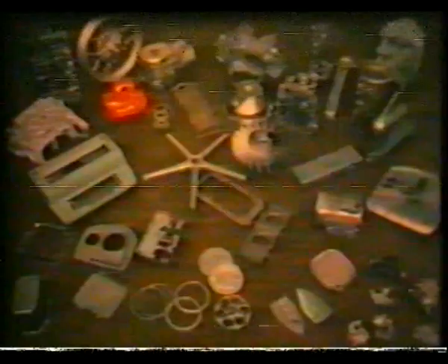The die casting process allows large series of non-ferrous components to be produced with great accuracy and very economically. In the process, molten metal is fed into the shot sleeve of the die casting machine and squeezed by the plunger into the die cavity. The liquid metal fills the die, duplicating the most minor details of the cavity. Even very complex and thin-walled parts can be produced by the die casting process.